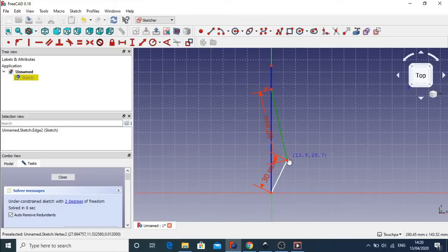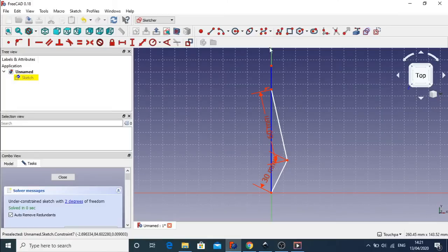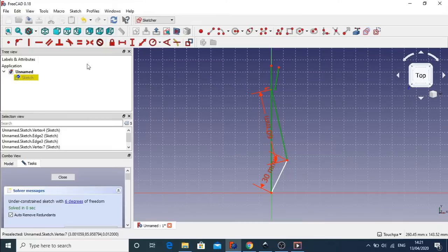And the last thing we need is the piston head that lays above. So if we look back at our animation, this piston head here, you can see where it's connected here. So we can just replicate that in our sketch, come off the construction geometry, and then place our piston head in and connect the points up. Oops, too many. Just those 2 points there.